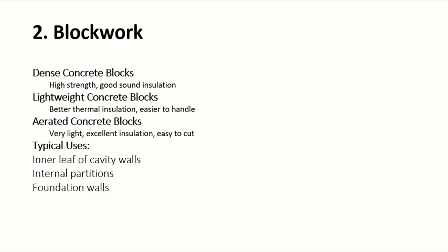When do we use them? Yes, I am coming to that. These aerated blocks are lightweight because of the content of the air. They are good where you need resistance against moisture, resistance against temperature, and so on. Because these air blocks will absorb these things, they will not let them go to the other side. So that's where we use them. They are lightweight and good for insulation, and in the end, easy to cut.